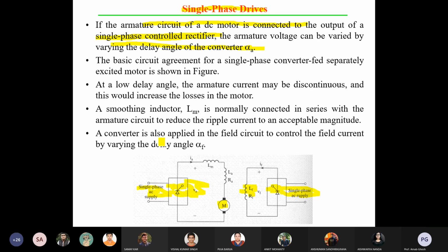After that, when the high frequency signal is 1 and the output of the ZCD, which is a square wave, is also 1, only in that region will you get 1. So you are getting a very high frequency varying signal, with a 0 to 1 variation, after the AND gate. Then what you need to do is use an option called monoshot. The entire cycle is not required, so you cut it and keep only a few portions of that signal.